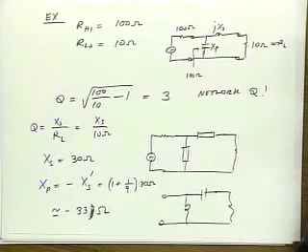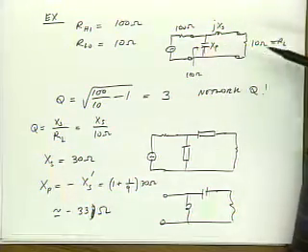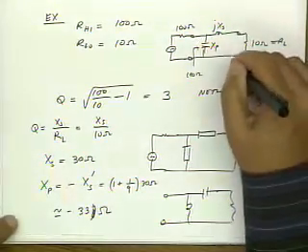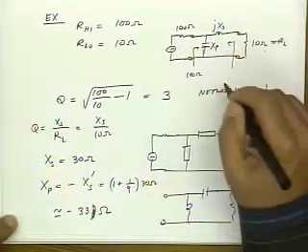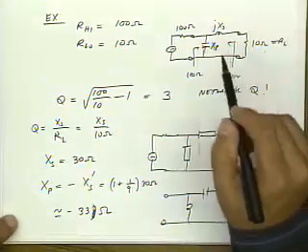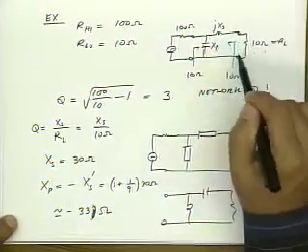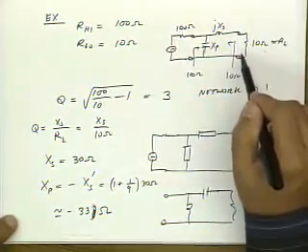Okay, well, this is a nice way of taking a low impedance and making it high impedance. What about the reverse process? How do I make a high impedance a low impedance? Any guesses? Yeah, the other way around, right? In fact, this is a symmetric network, right? It transforms 10 ohms to 100 ohms. But if I look here, it also transforms 100 ohms into 10 ohms, right? That should be obvious from power matching theorem. If I'm extracting the optimum power at this point, since this is lossless, I must be also extracting the optimum power at this point. So if I just flip this around, it does the opposite thing.